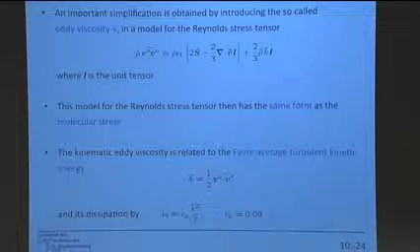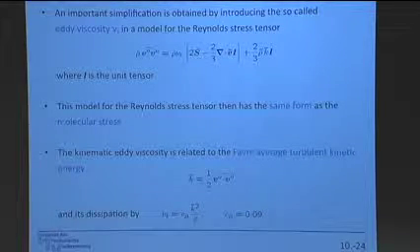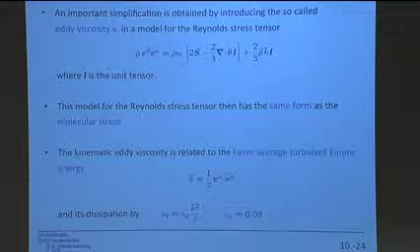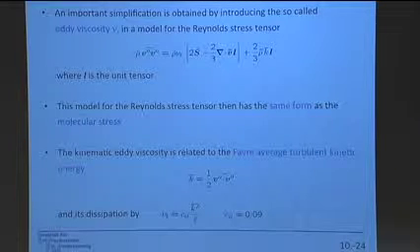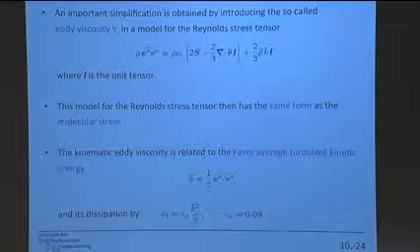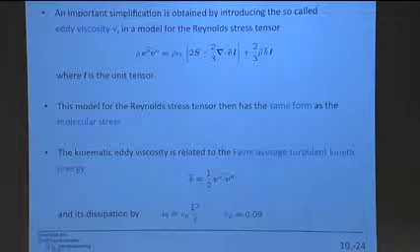What units does it have? Just from listening to the term, you can guess: it must be kinetic energy per unit time. What is kinetic energy per unit time? That would be meters squared per second cubed. So that's the unit of this dissipation rate, and just by dimensional arguments, you find that nu t is k squared over epsilon.